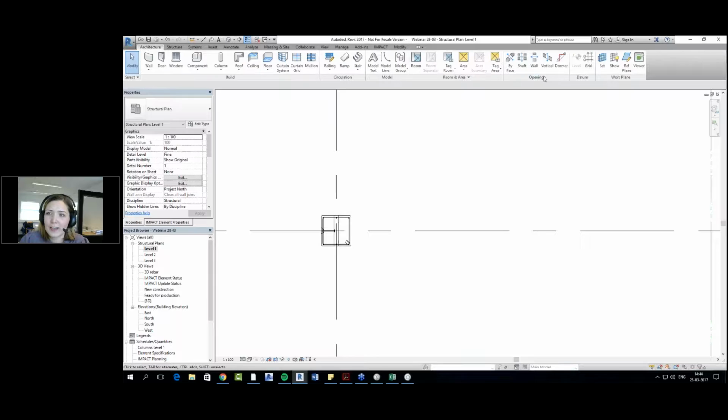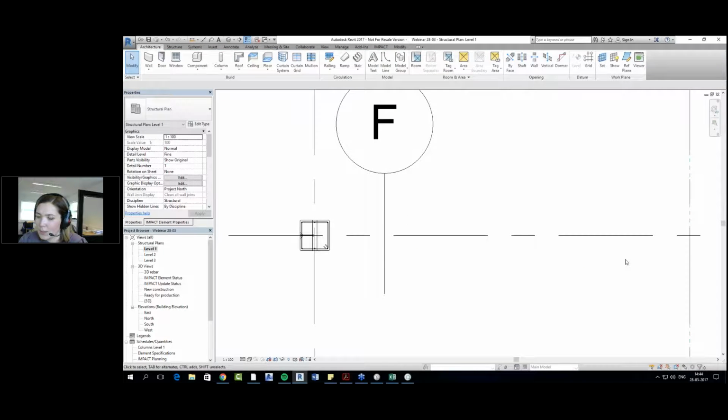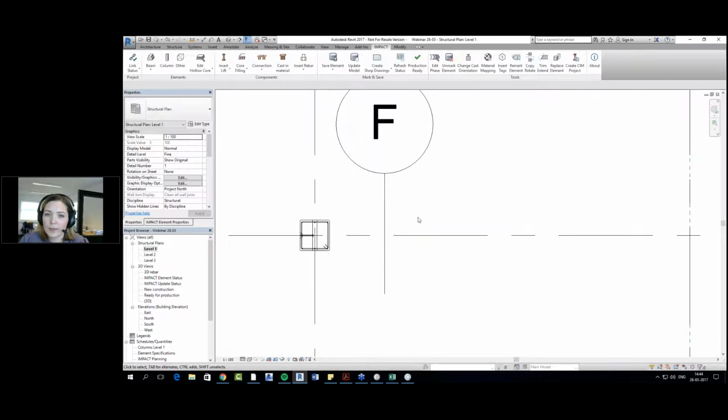And if we say grid mirror, okay, let's try to mirror this column by using copy rotate and choosing the axis. Yes, it actually does, because this is also family and it rotates the reinforcement. So it takes the whole assembly and rotates everything as it's included in assembly.